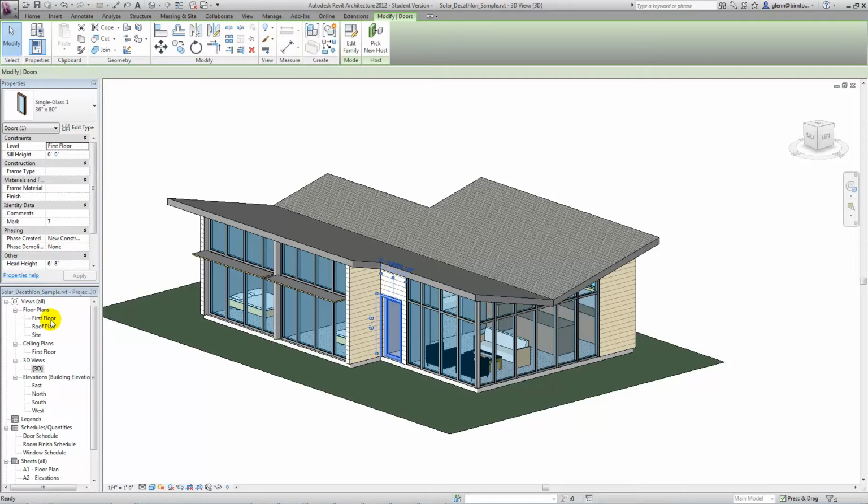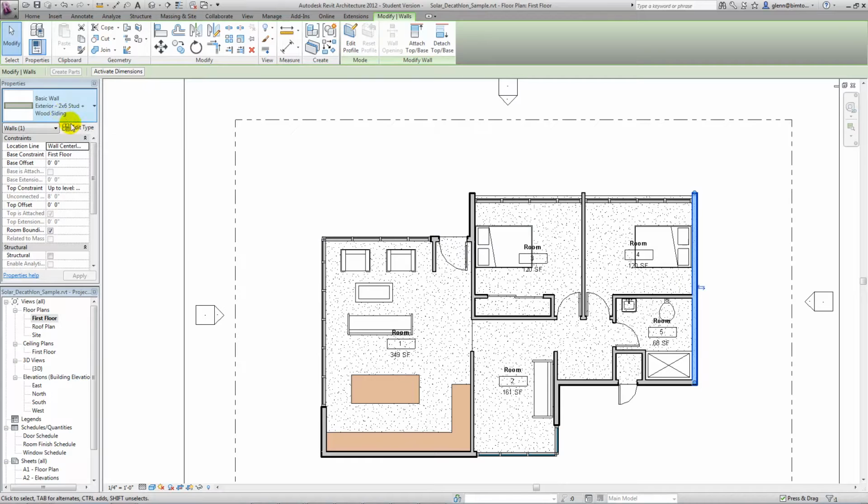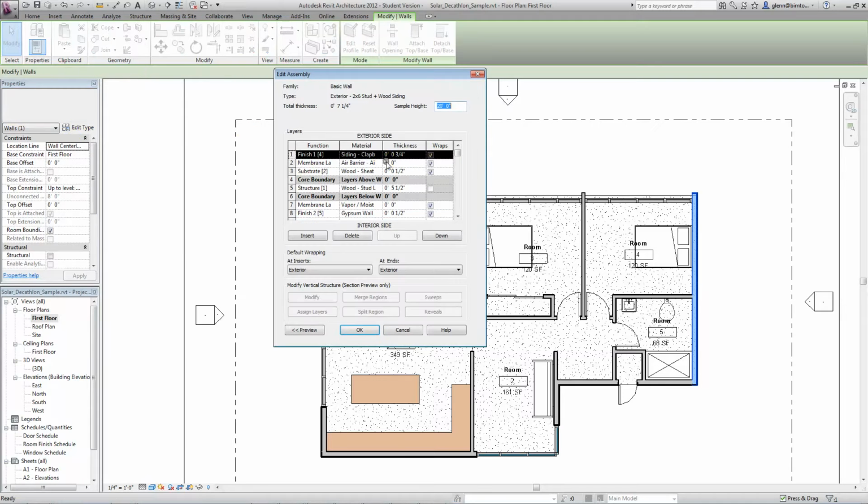And as you go through and do your modeling, it's going to start with basically doing the building elements and thinking about the surfaces. For example, each of these different walls has a structure to it. It has kind of a layering to it of all the different materials that are in there and the thicknesses. And one of the really cool things that's actually happening now in Revit 2013 is these wall assemblies are actually very smart about the thermal properties. So for each of the different materials, we can actually assign what the U value of each of the different materials is, or actually it's the thermal resistance. And then it'll go through and calculate a composite U value for the wall based on the actual thicknesses. So it's really getting quite smart about saying it's not just an architectural model, it's also an analytical model. Okay.